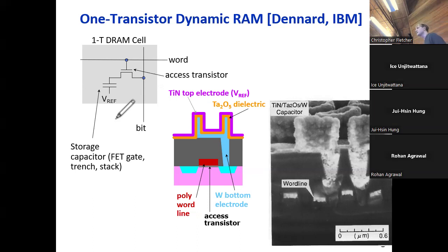perform some asynchronous, what they call refresh operation, which refreshes the value that's stored at the cell. So basically what a refresh is, is just a read that occurs to any DRAM cell whose contents you want preserved at a particular interval. So imagine I want to read this cell. I can read it just the way that we described, but sometime in the background later, when I'm not reading it, a circuit which accesses the DRAM is going to perform what is tantamount to a read as well.